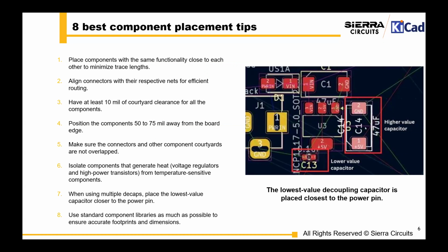If you're using any force on the breakaway tabs, that could damage the board or even lift the component. So having a good clearance from the edge of the board is great. And if you can't maintain that, don't have a breakaway tab there for any extra mechanical force in singulating your boards. I think that's a really important one where I've seen some root causes.